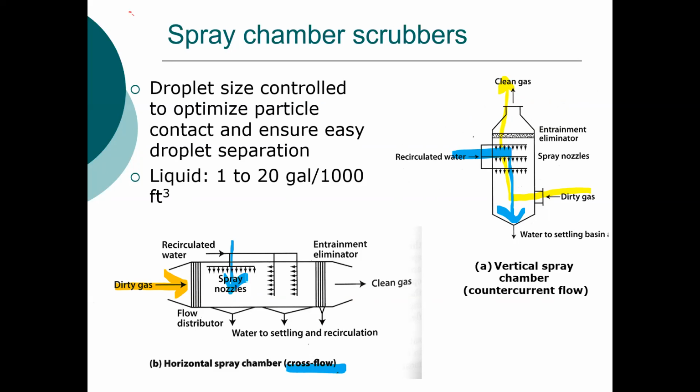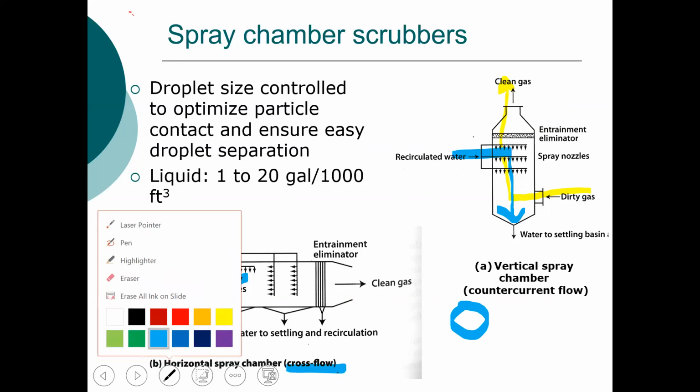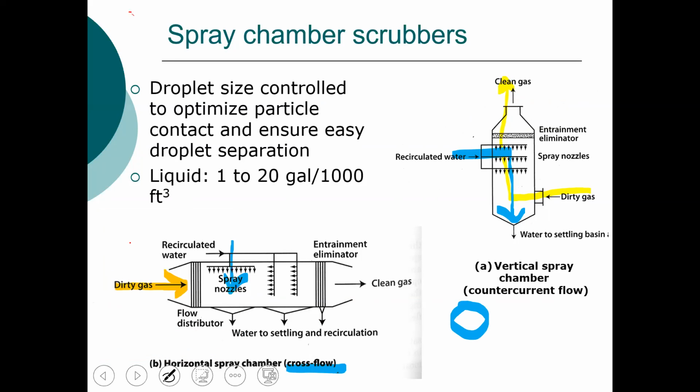So this really is a phase transfer, because if I draw it here, here's my water droplet. I'm going to switch to the pen. And I have my particles out here. What I'm trying to do, or in the case if I have SO2 gas, I'm looking at transferring those particles, I have to have a collision, and I want to transfer it into that droplet. So the longer I can suspend that particle, the more opportunity there is for mass transfer.